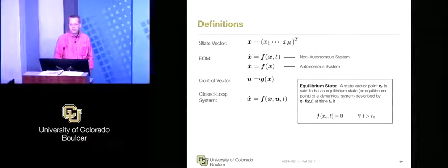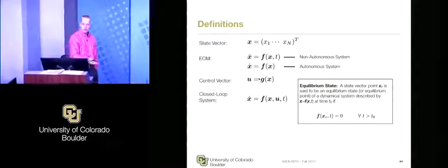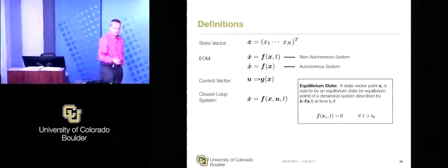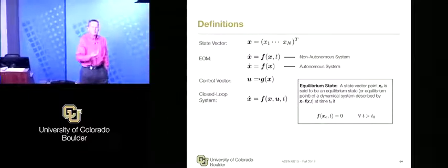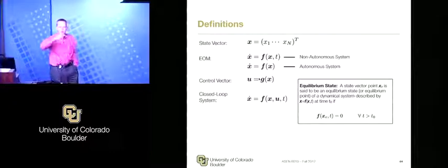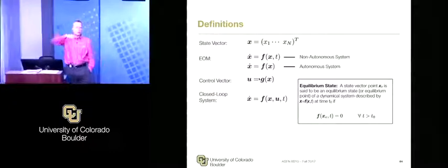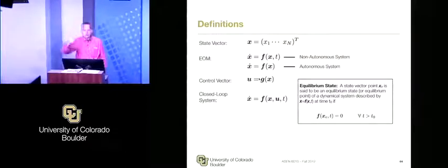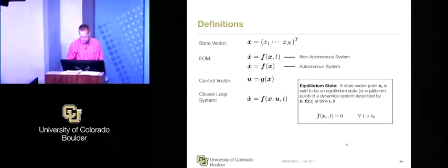And for attitude dynamics, we do the same thing. There are naturally occurring equilibria, which we've seen. There's relative equilibria if it's relative to a moving frame. With torque-free motion, we saw that spinning about axis of major inertia was actually stable. And if you're perfectly spinning, it just continues. All the rates, accelerations go to 0. So that's also existing there.